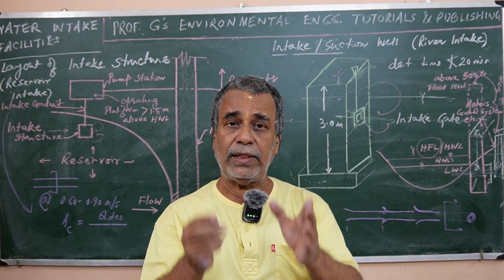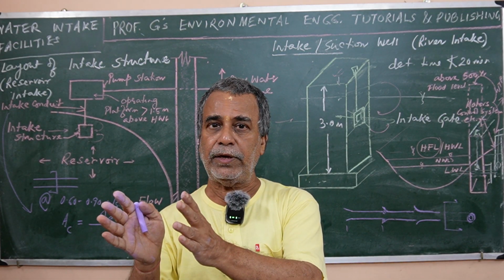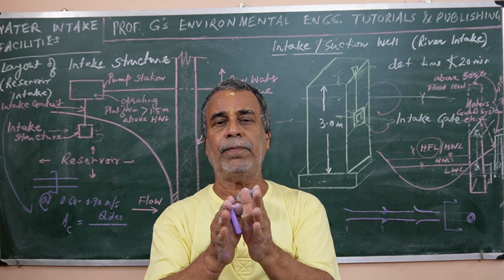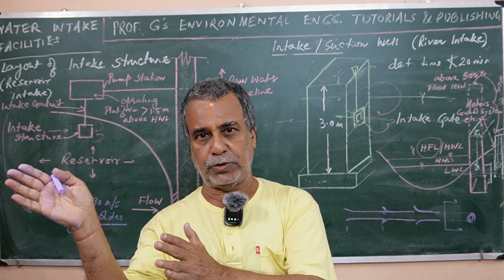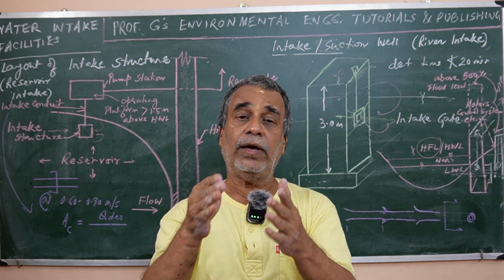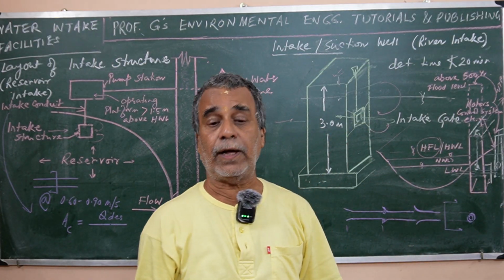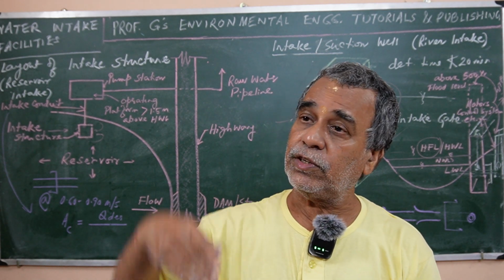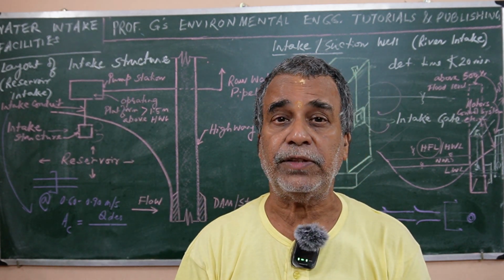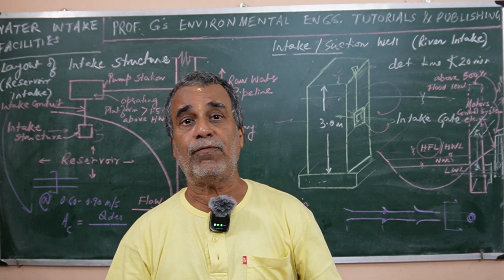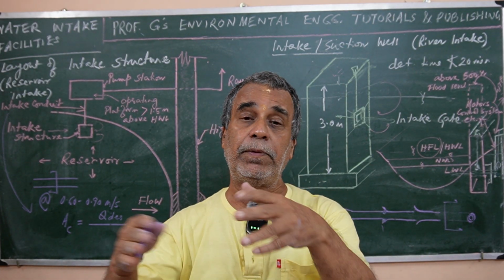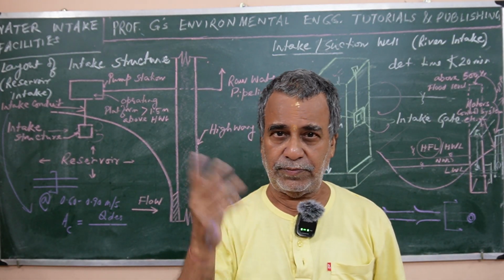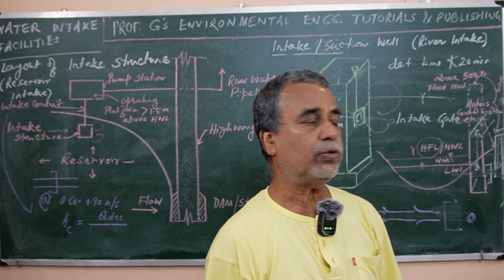So that is why the mechanical parts, including the pumping system, are to be designed for 15 years or so, right? But for the civil structure, like the intake, there is a 60 years design life. So 60 years, at the end of that, it must meet that. But by that time, say 4 times you might have to replace the pumping system. You have to replace, right?